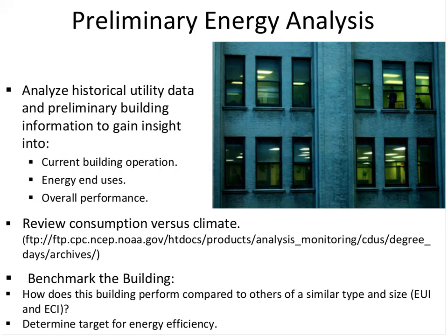So when you do the preliminary analysis, you're going to analyze the historical utility data. You're going to gain insight to the building by looking at this data. You're going to look at its current operation, its trends, what's the schedule of the building? Is it open 10 hours a day, 12 hours a day, 24-hour a day operation? You're going to get a feel for some of the energy end uses in that building, and then you're going to look at its overall performance. And we'll talk about how to get this in a second.